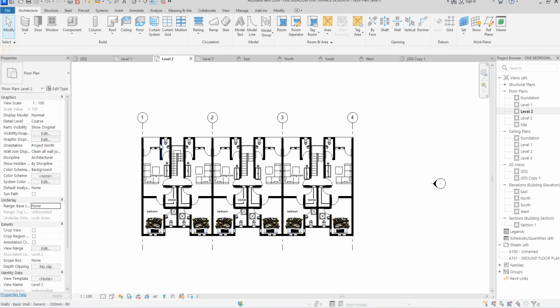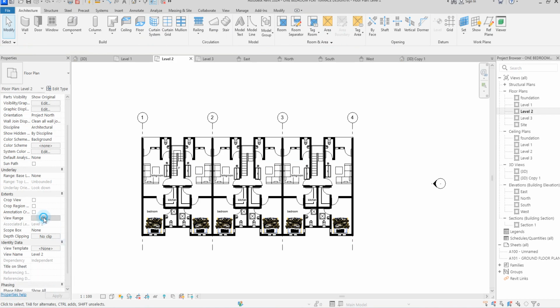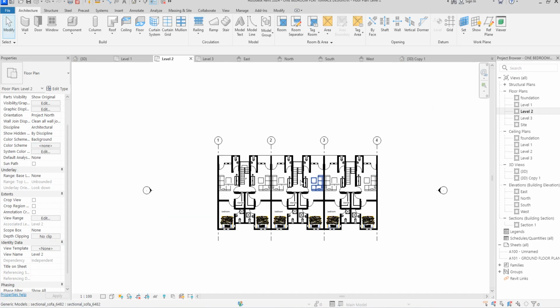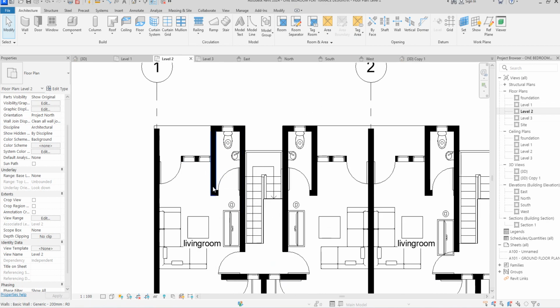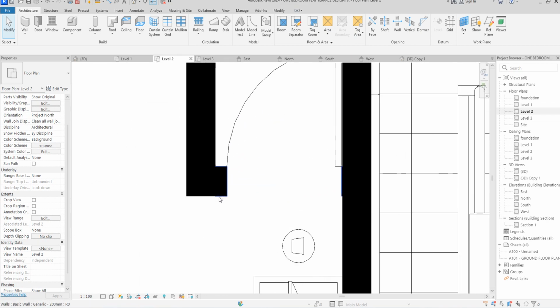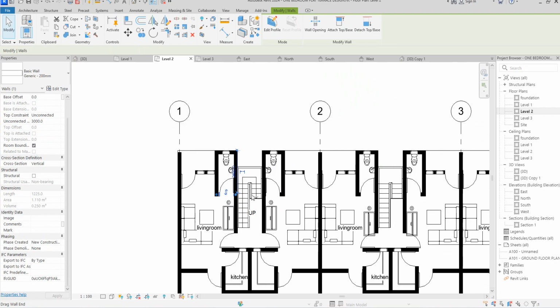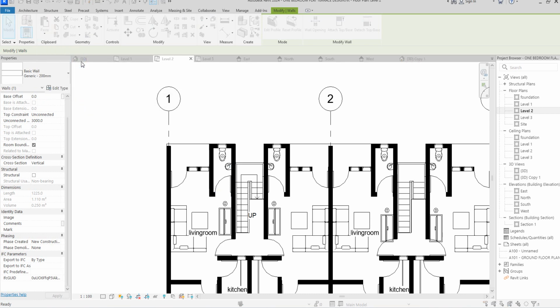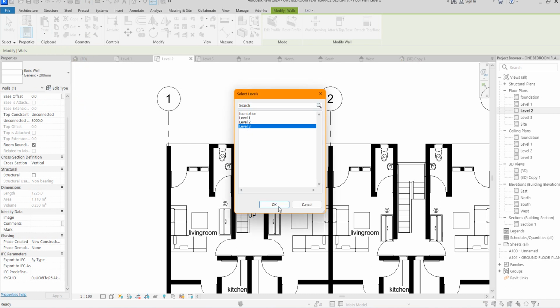elevation fill is none. Good, which is okay for me. So fill region, check this if it's at the normal cut position. So now it's there. So what we do now, we go to elevation, then go to the elevation, and this particular wall need to go up, because that's the way we want to do the work effectively. So I'm going to say copy this, copy to clipboard, then paste to align selected level. So I'm going to paste it at the level 3.